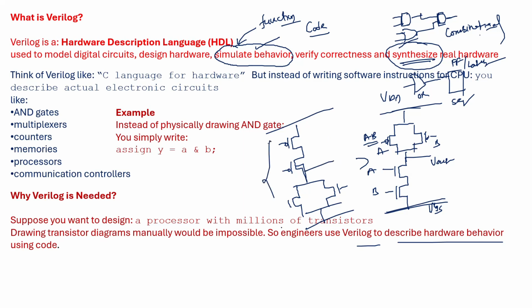But whatever functionality it is doing here is the NOR gate operation. For this, we simply write the NOR gate, and whatever inputs we give, I am getting the NOR gate output, A plus B whole bar. This is the output operation we are getting.